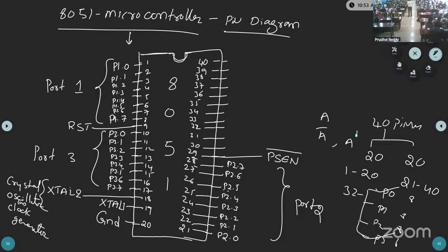That is the reset. It will terminate all running applications and executions and reach the initial state. That is the reset pin. So everyone remember this? Bar means active low signal. Okay, so the 29th pin is an active low signal, and the 30th pin is address latch enable. We'll discuss one by one in the next. ALE stands for address latch enable. This is the active high signal, and the next one is